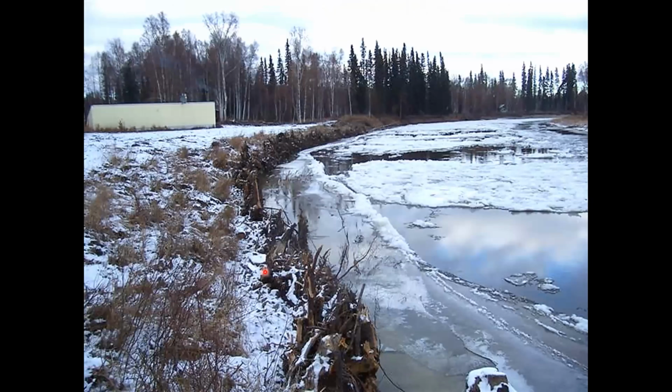Most people don't believe that this holds up well to ice scouring. I wish I had the video of this. This landowner actually sent Mitch and me a video showing that these ice sheets were just bouncing off and not even touching the root wads. The root wads had slowed the velocity along the river enough that when these ice sheets would come down, the outside velocity would just pick them up and spin them. So they were just spinning as they were going downstream.